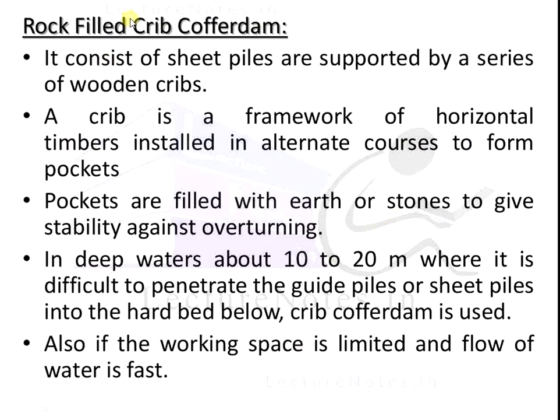Next, the rock filled crib cofferdam. It consists of sheet piles supported by a series of wooden cribs. The crib is a framework of horizontal timbers installed in alternate courses to form pockets. The pockets are filled with earth or stone to give stability against overturning.